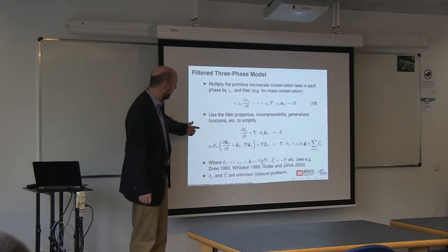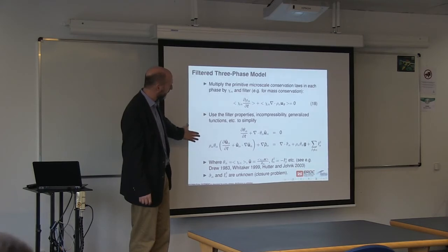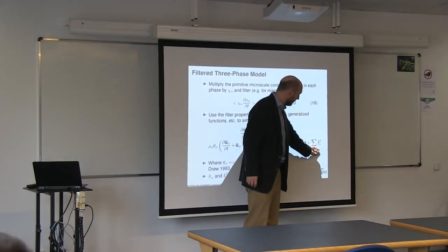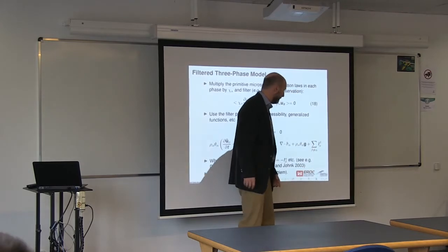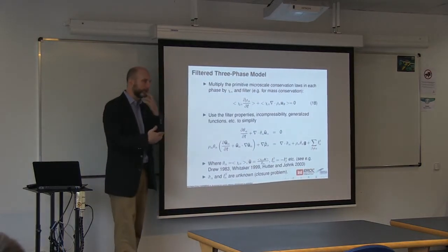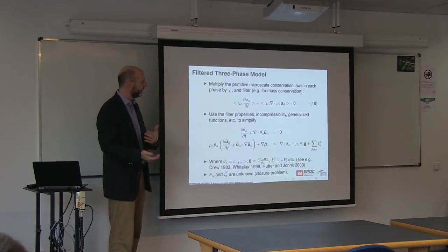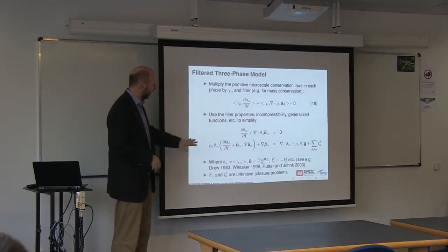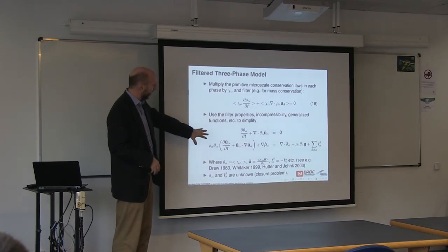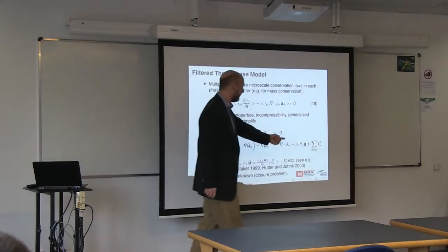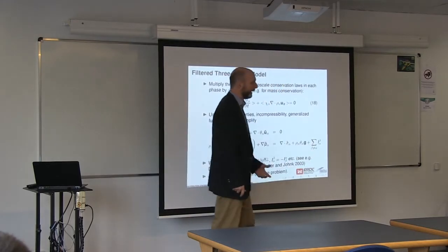So in this case, when we go from the small scale to the large scale, we end up with new source and sink terms, which are the transfer of momentum between the fluid phase and the solid phase, and vice versa, and also between the air and water phase. If we're just thinking for simplicity about water and solid particles, then these are effectively the upscaling of the drag and the lift.